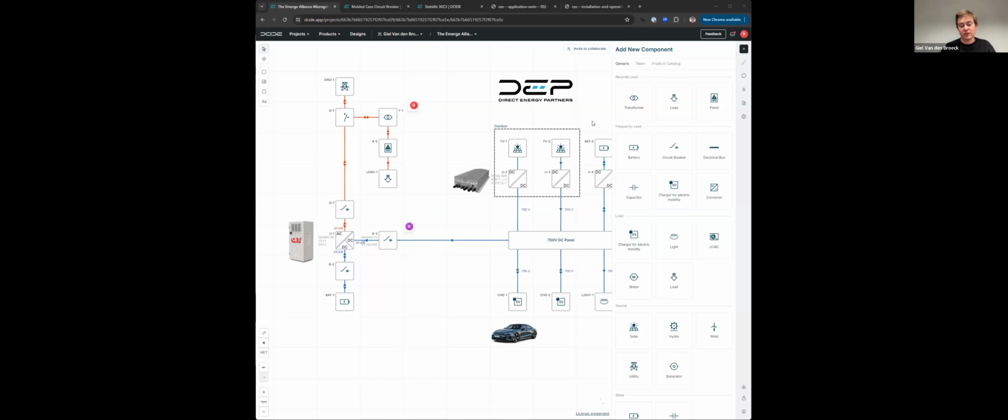If you want to achieve the same level of reliability in an AC microgrid, you will end up having quick transfer switchgear in between, and that does exist, but because of these requirements, it will end up being pretty expensive as well. And then as soon as you want to reconnect back to the utility, you've got to synchronize, match the phases, etc. So that process also adds more controls, more complexity, and ultimately adds to the cost of the entire system.